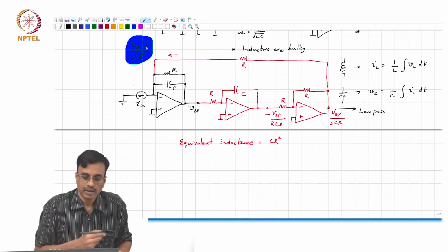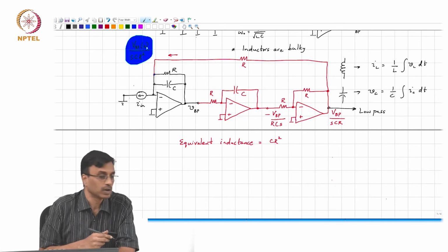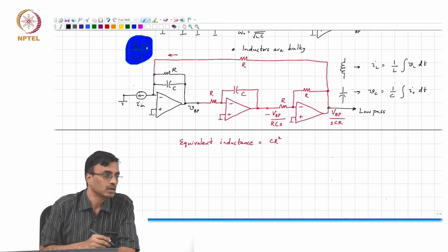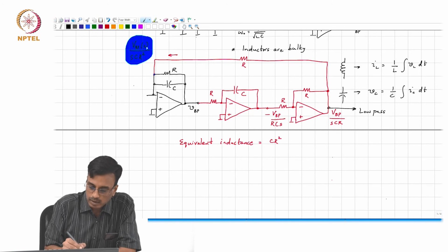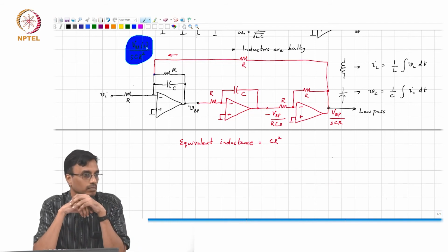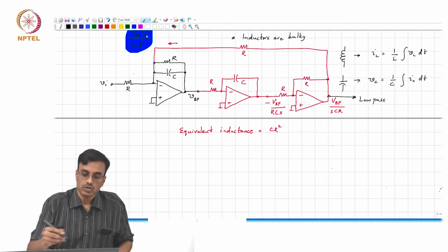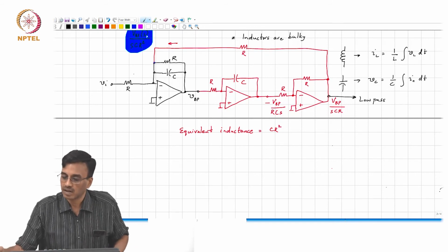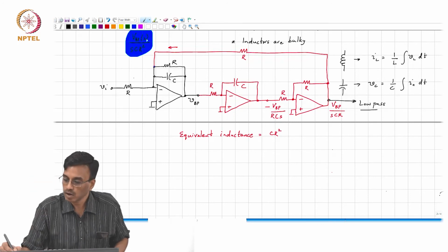And the last thing is that we'd like to have voltage input, voltage output. So, if you wanted the input to be a voltage but not a current, what do you think you can do? Well, that's straightforward. Basically say, oh well, this is R and this is R. Okay. So this basically represents a second order low pass filter at this node.